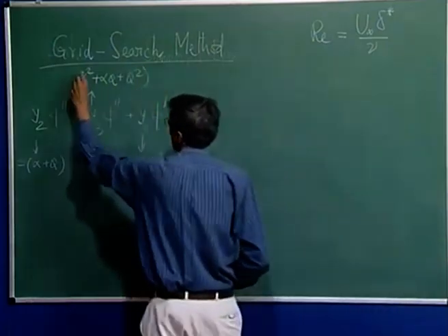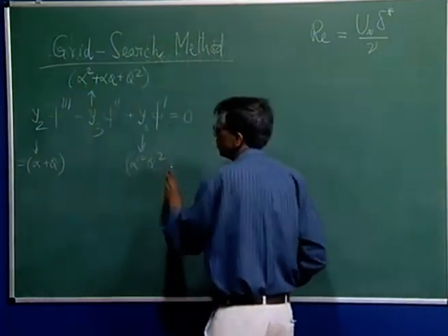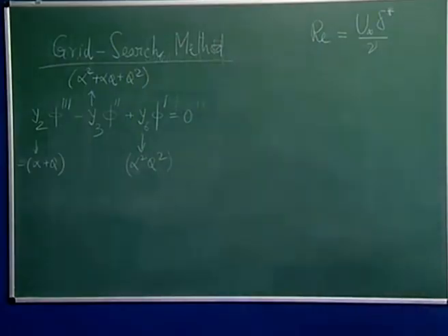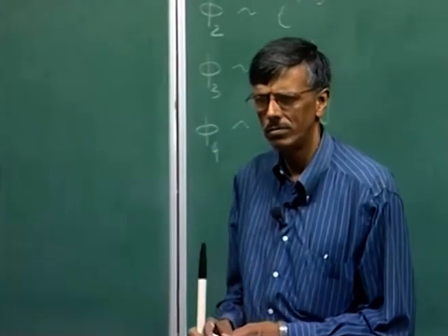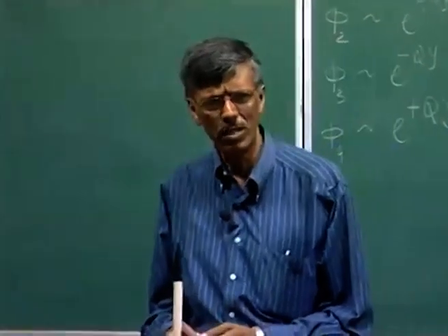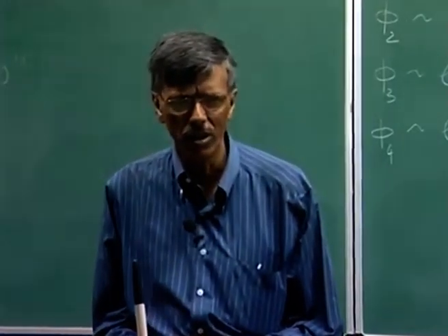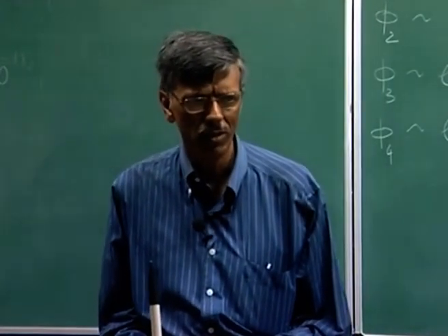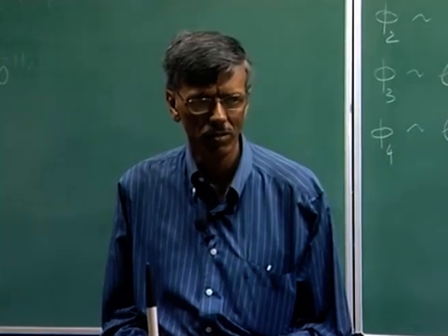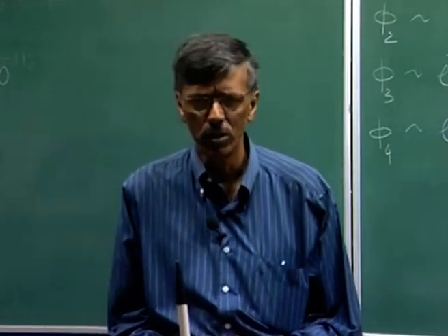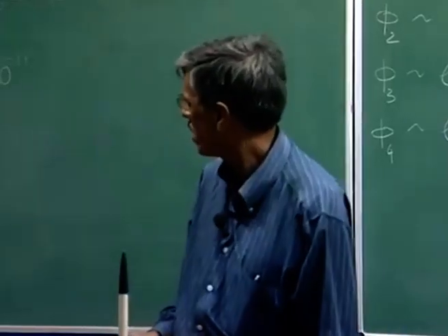So, these are those 3 coefficients, and you will have 3 roots, but wait a minute, what did we start doing with the compound matrix method? We only talked about 2 modes, the ones for the wall modes which decay with y, and this is a third order equation.